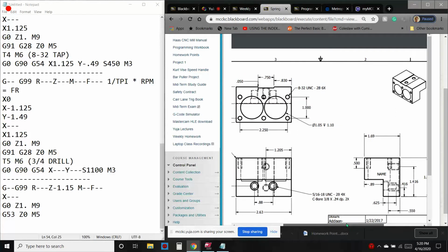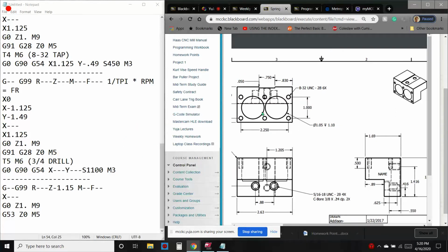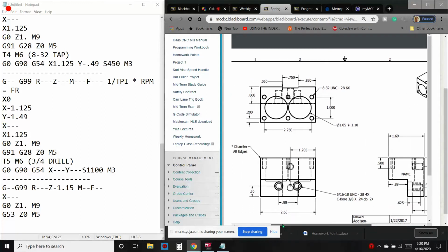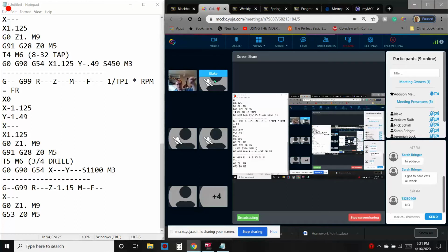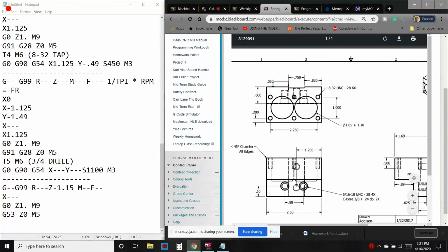what we need to do next is determine what size end mill we're going to use to cobble these holes out in a helical way. By helical, I mean we can do a circular interpolation where the end mill's making a circle in X and Y and also moving in a Z minus way. And this is a really great way to remove material out of a bore because you don't particularly need a center cutting end mill to do this because it's doing kind of a ramping feature, except it's in a circle. You do this all the time.